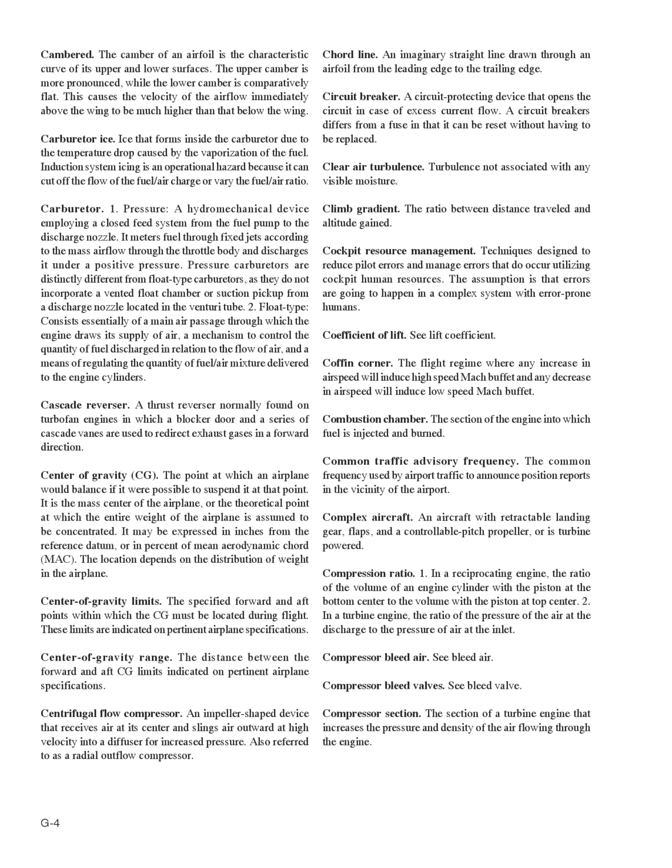Coffin corner. The flight regime where any increase in airspeed will induce high-speed Mach buffet and any decrease in airspeed will induce low-speed Mach buffet. Combustion chamber. The section of the engine into which fuel is injected and burned. Common traffic advisory frequency. The common frequency used by airport traffic to announce position reports in the vicinity of the airport. Complex aircraft. An aircraft with retractable landing gear, flaps, and a controllable pitch propeller, or is turbine-powered.